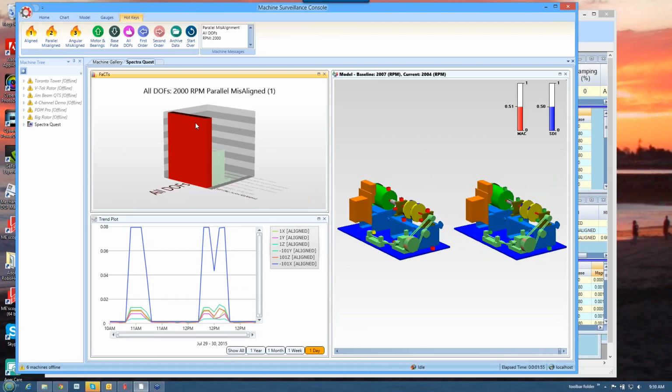but just thinking about integration of a shape, we're simply going to be dividing by the frequency of the shape. And so that's not going to change the shape. It's just going to scale the numbers down. So the shape itself should come up with the same MAC values, and the SDI values now are going to be displacement numbers, but they're all simply divided by a constant. So the shape, the numbers are not going to change in terms of whether SDI or MAC will indicate a difference. But yes, we could do that.